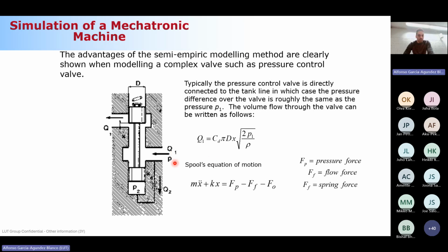How do we control this? You can see that you have a line that communicates with this chamber, so that you can send here a volumetric flow rate Q2 and this P2. With the balance of the elastic force of this spring with the pressure force coming from this chamber, you can adjust the motion of this piston, okay?